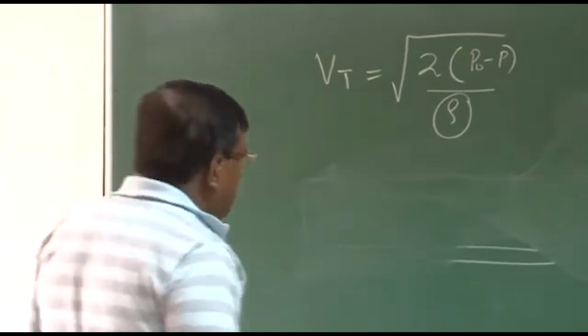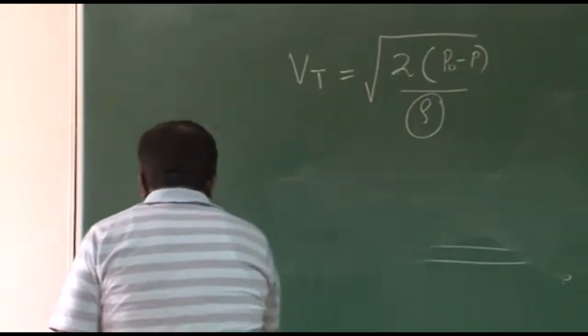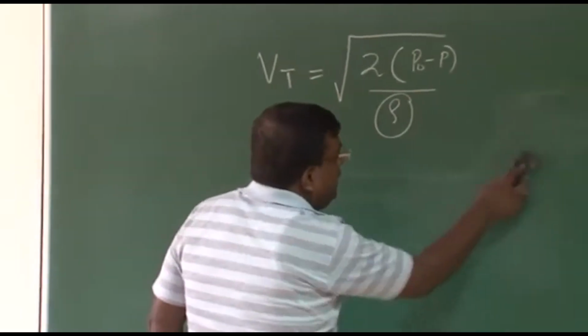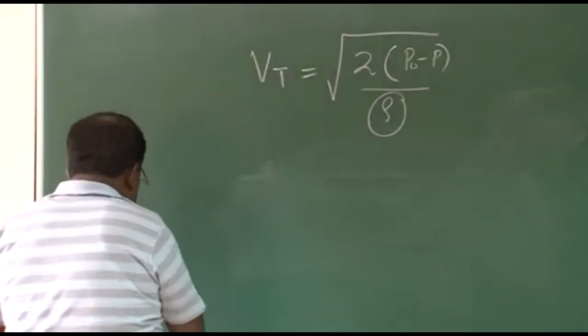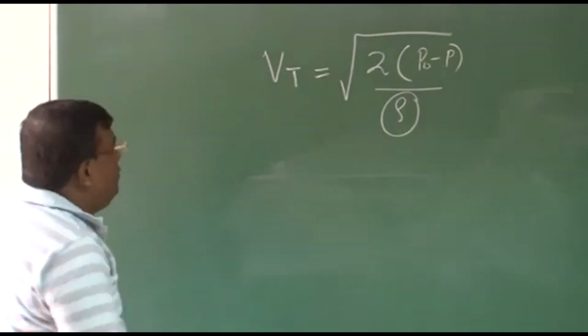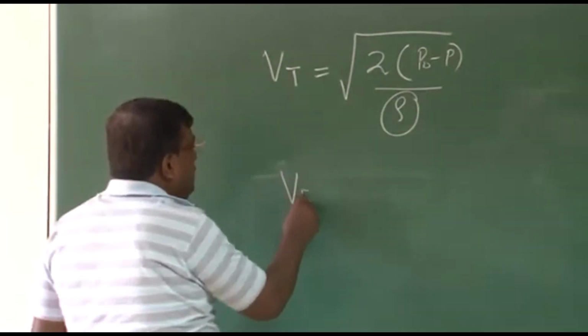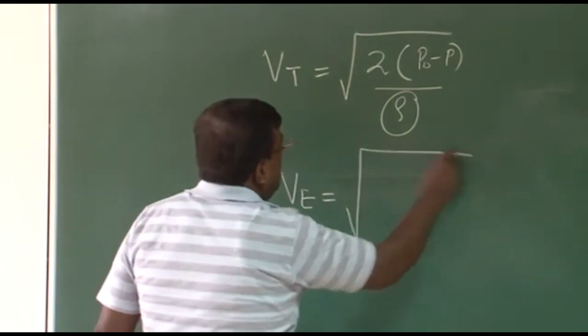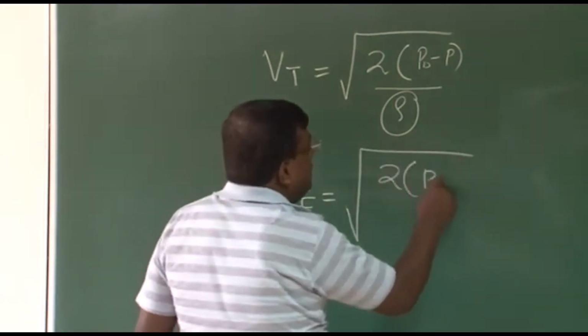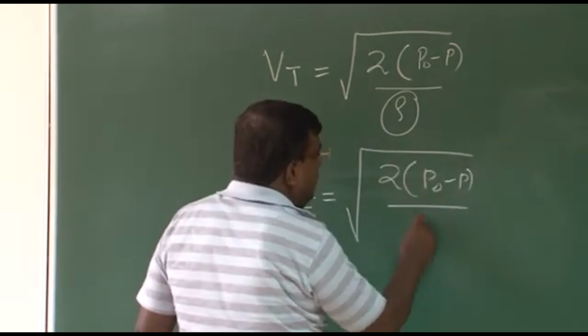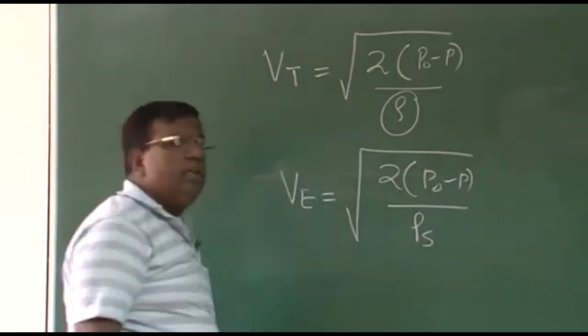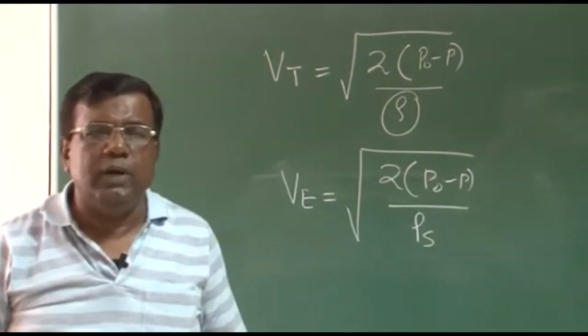But for calibration purpose, you could understand that if every altitude has a different density, then calibration will be a difficult thing. So we have defined some speed V where this is the same dynamic pressure, however rho is rho s, which is the sea level standard atmosphere value.